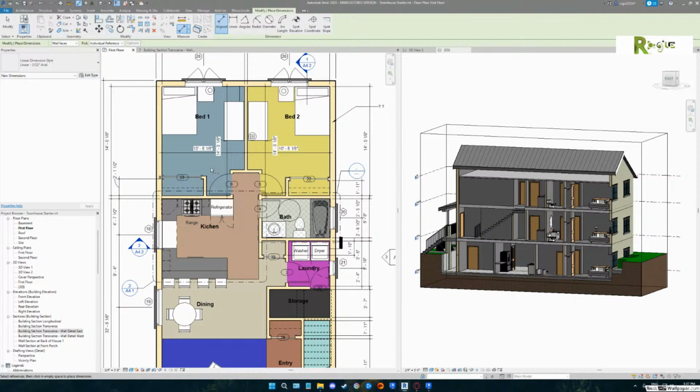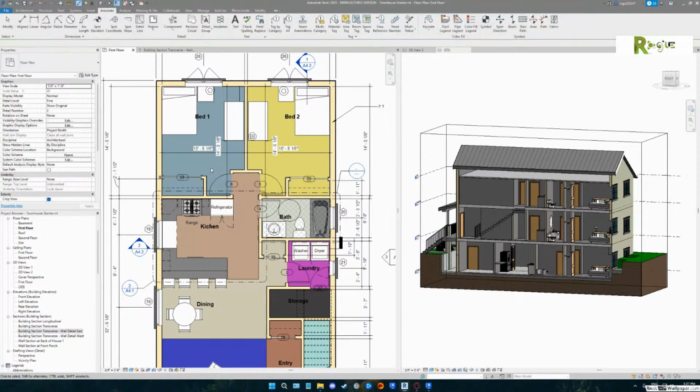Because they're already down, you have all these countertops, toilets, bathtubs. And when you think you're dimensioning to the edge of that wall, you're actually dimensioning to the edge of a tub or the edge of a sink, the edge of the lip of the tub or the line of the range. Exactly. So what you do before you go slinging dimensions is escape 2 times, pick one of your walls,